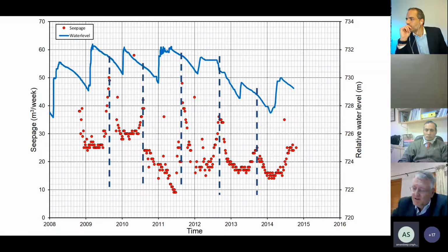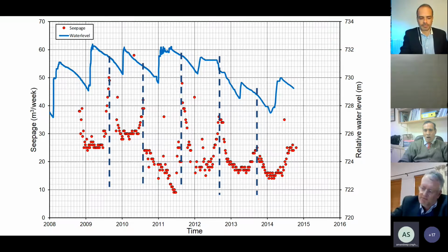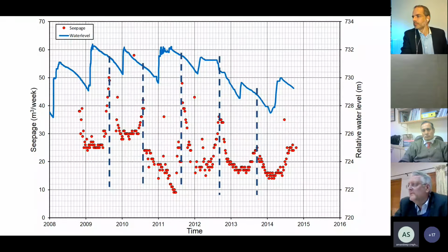In many arches, if you know about arches, we do see this. So from now on, we will monitor it and see if there's any increase in seepage rates during the same conditions. If you work with an arch, you want to see whether your grout curtain is still functioning and whether you see something like this.